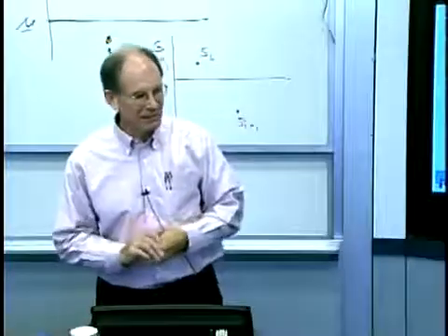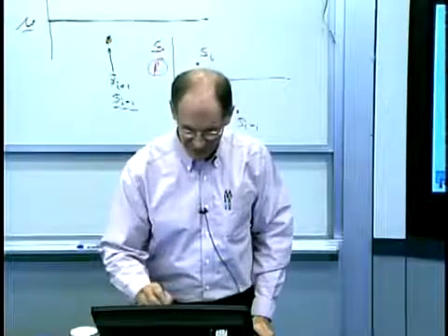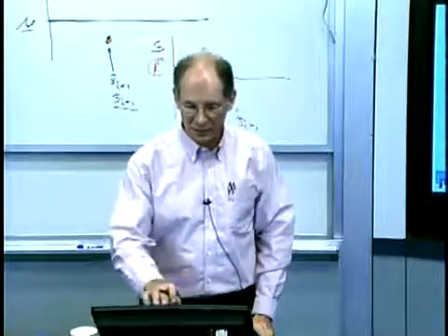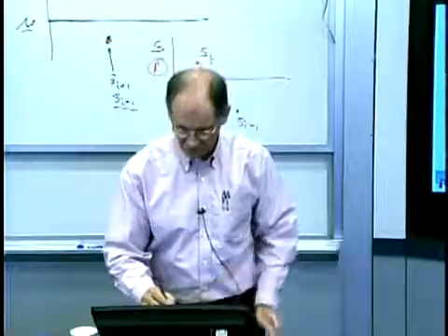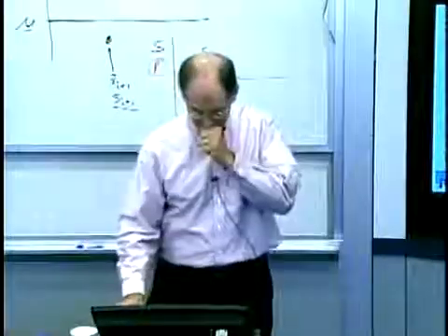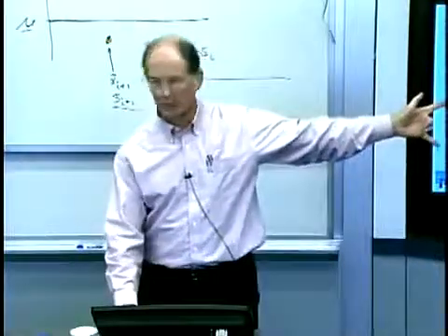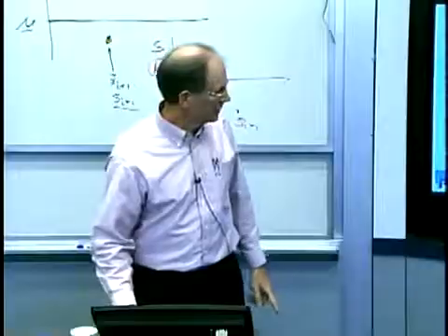But it's a little bit simplistic, because it is possible that you'd get a process that's perfectly in control and you'd have one point that's up here. It's just not probable, but it's possible. So we can do a little bit better than that. And again, we can do the same thing with the S-chart. We can do upper and lower control limits.